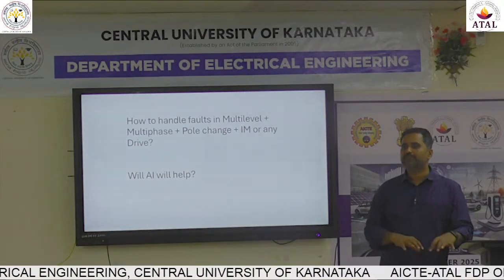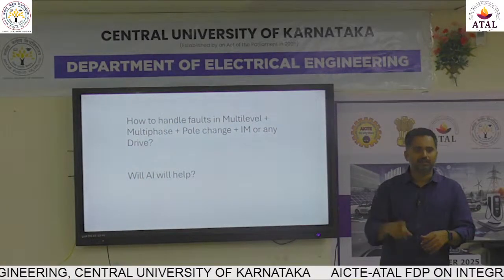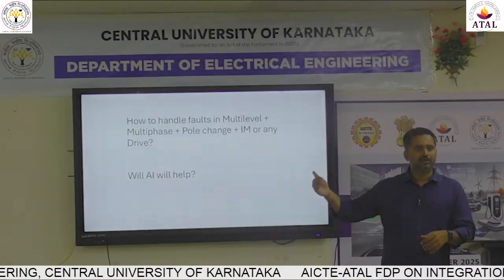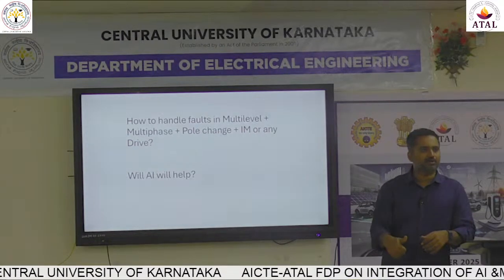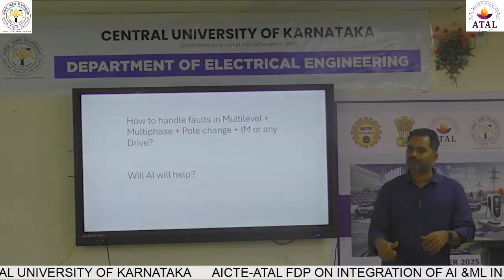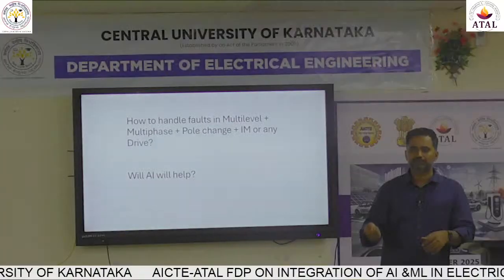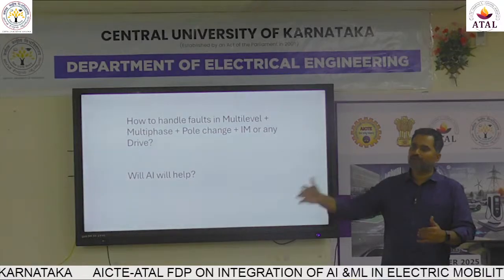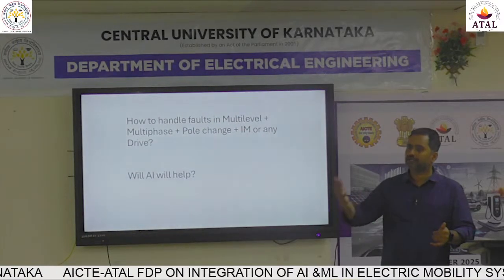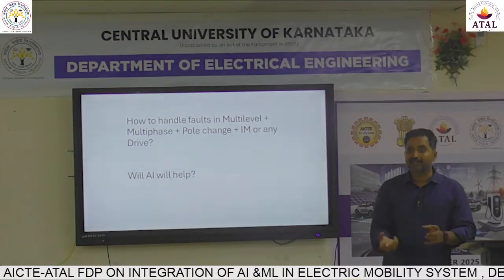People think that PMSM is a great help at the time of starting, but at higher speeds you have to demagnetize the rotor flux. Demagnetizing the rotor flux or reducing the lifetime of permanent magnets is another big issue. So it is not that one is good and one is bad. That is the reason they are coming with permanent magnet and electromagnetic together to address these issues.